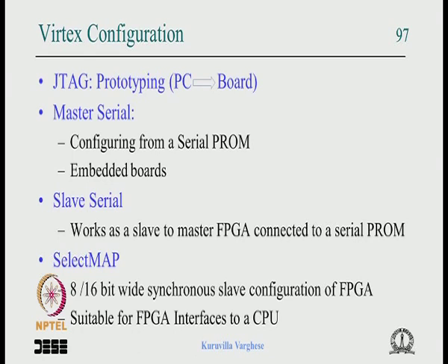It is a committee's name, which came out with this particular port, called the Joint Test Action Group. That is also called TAP, the test access port. That is also called boundary scan, because that port was developed for the continuity check on PCBs with very complex packages like BGA.